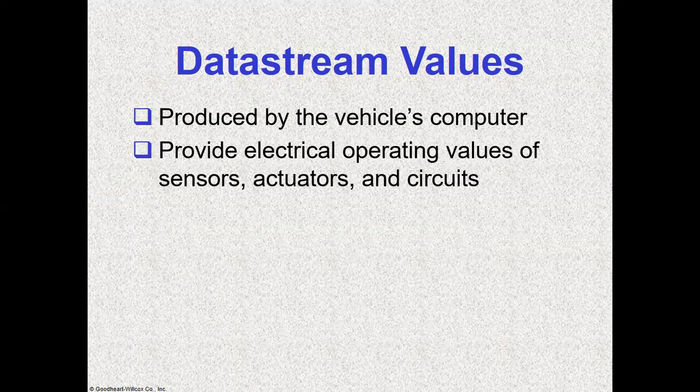And if it's a GDI system, we can see the fuel pressure at idle and the fuel pressure at different RPM ranges. On a GDI system we can't use a fuel pressure tester to test the fuel pressure, because with these systems at idle, sometimes we'll be seeing a minimum of like 500 psi.